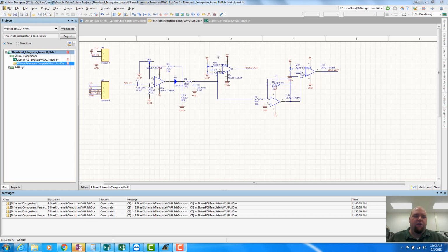So I'm going to go over sort of what I'm going to be showing today. This board receives a signal from a preamplified acoustic microphone, and I already did the schematic here. You might recognize this connector from the previous acoustic amp preamplifier, where it's got a positive 12 rail, negative 12 rail, signal rail, ground. This is the power that's going out to that external preamplifier and the signal that's coming back from that preamplifier.